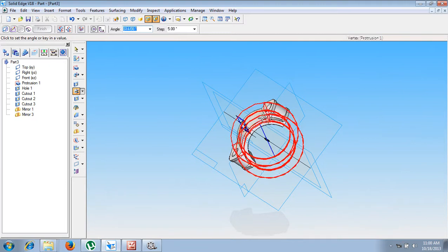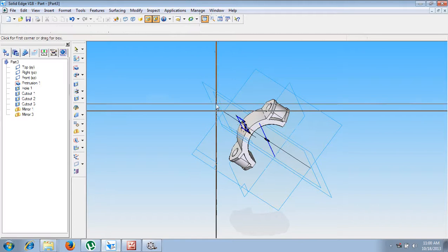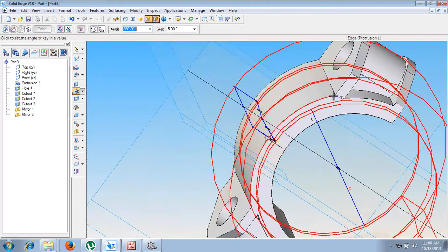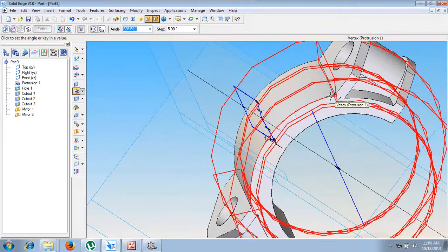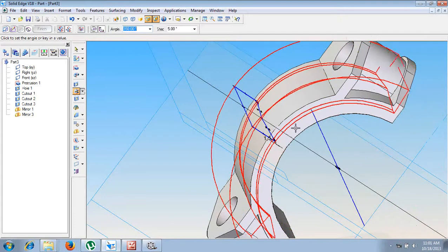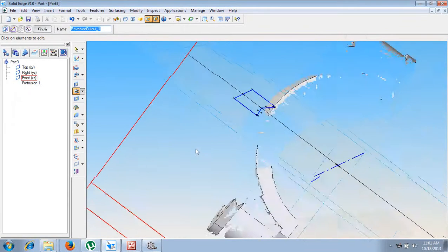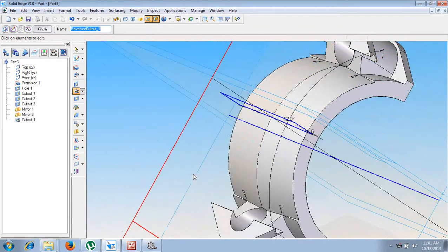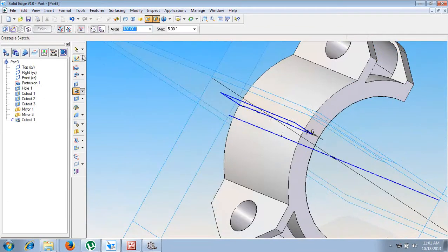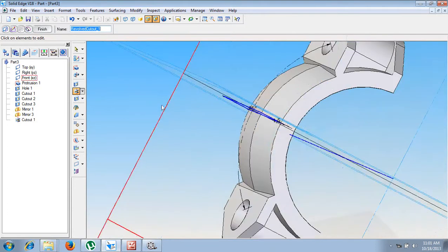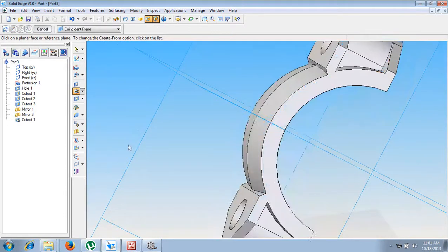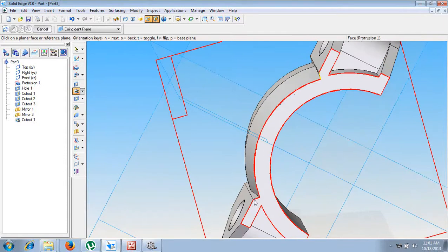What is the angle of cutout? Let me show you. The angle of cutout should be some value. If I come here, it is showing us 625. Let me give 120 degree as the cutout. Okay, you can see what is happening with the 120 degree cutout. Now instead of that, make it 95 degree. Now you can see yes, we are getting it properly. Now say finish. After making 95 degree, you can see here some portion is getting lost.